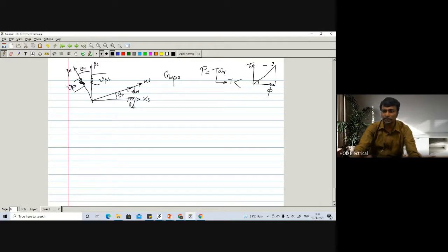So the current has these two components, torque and flux. Accordingly, whenever the two winding axes, stator and rotor, carry stator and rotor current components perpendicular to each other, the speed EMF term will be maximum. Otherwise, the speed EMF term will be minimum.